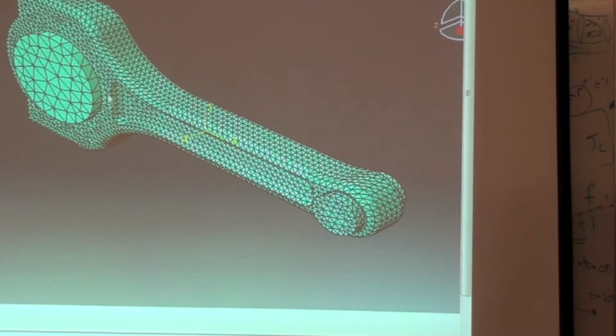So this is the mesh I used. You can get finer, but if you get too fine, you don't have enough elements. I think it's maxed at like 100,000 or something like that, or 10,000. So you can't go extremely high. Obviously, there are ways to improve this. First of all, this analysis is symmetric, so technically you could just cut it in half and not have the other half, if you want to optimize this.